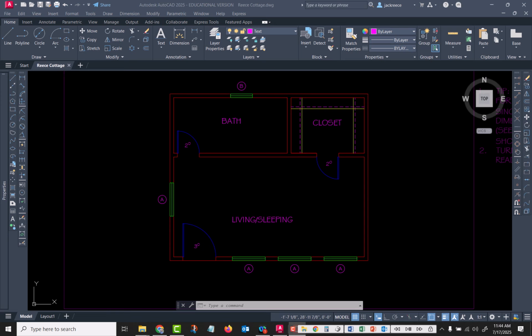You can set the scale to it, you can set the angle to it, and usually picking points inside an area to be hatched works pretty well. Okay. Sometimes there are some problems. The issue being you have to have a closed perimeter in order to have a hatch.